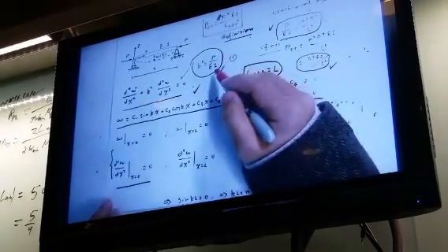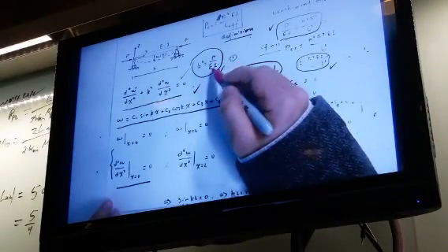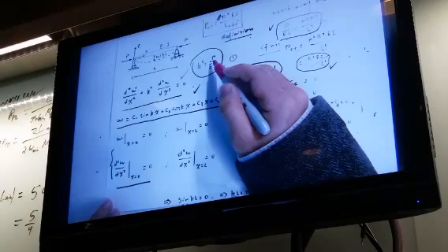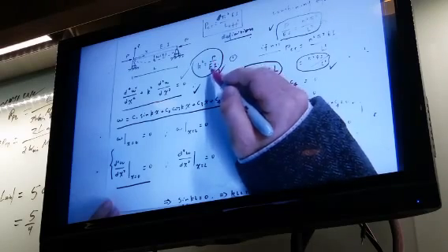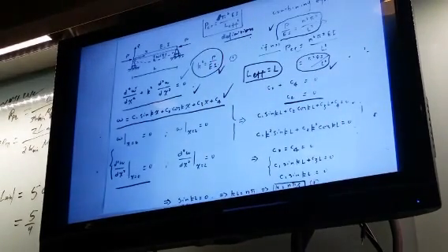And the K is defined as P divided by EI, K squared. P is the loading, the critical loading we are trying to solve. E is the modulus, I is the area moment of inertia.